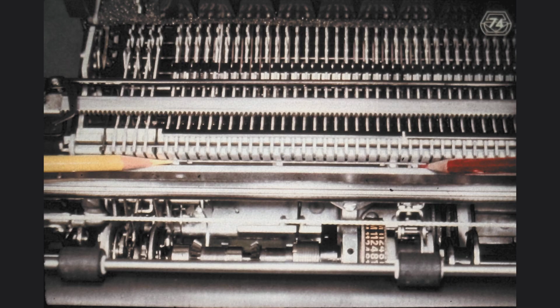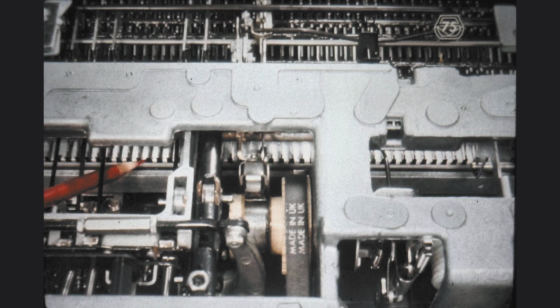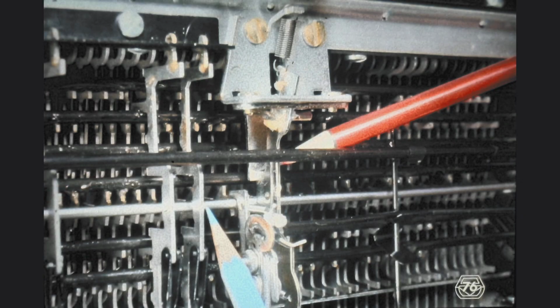These are the screws which hold the interposer latch springs in position. The interposer latch springs also come in 2 sections, each covering half of the total number of interposers on the keyboard. As mentioned before, the best way to observe the interposer latch springs is by tilting the machine approximately 120 degrees top to the rear, and then observing the rear of the keyboard. They cannot be seen from above because of the protective shield which completely covers them.